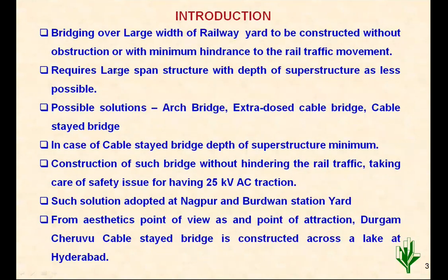So generally there are requirements of a large span. In case of rivers having very large flow, where constructing a foundation in between is difficult, we choose a longer span. In cities, nowadays there are railway yards, and we are building a bridge across a railway yard to cross that railway line. Keeping smaller spans with foundations in between the tracks is becoming difficult for construction.